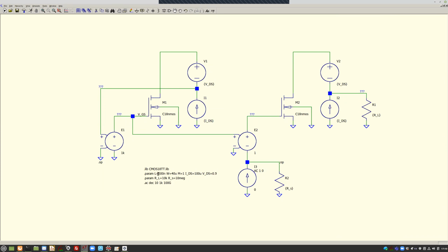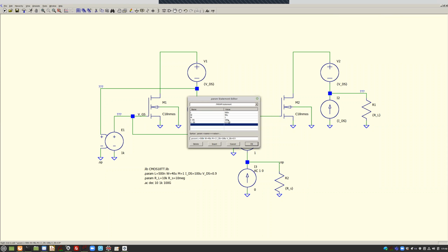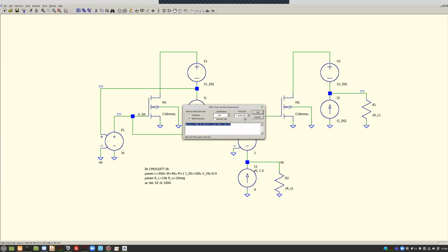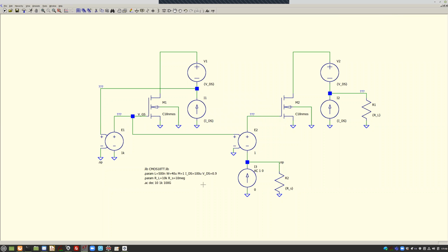And here you find the parameter definitions, the length and the VDS and the operating point that I want, everything. So here this device is biased, and this voltage controlled voltage source generates the voltage VGS required to generate here approximately 0. You can see that.